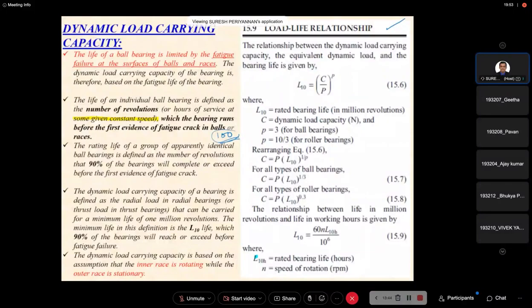I mean, a non-destructive method, the X-ray method. There are different methods for testing the bearing: X-ray images, a non-destructive method, and the ultrasonic method, also non-destructive. Under non-destructive methods, X-ray and ultrasonics, and also thermography. We are testing the bearing while the bearing is working.